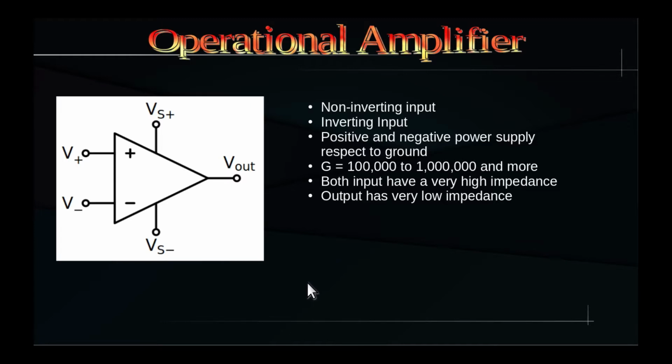Thanks to these properties, op-amps are able to amplify extremely small signals, and to avoid bringing them into saturation, we usually need to put them in a circuit with a strong negative feedback to limit the gain to reasonable values. Because there are two inputs, and because the output depends on the difference of these inputs, they are applied very often in circuits where it is necessary to provide a strong noise cancellation.